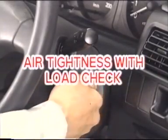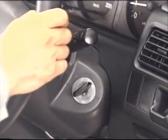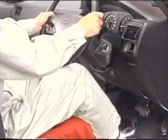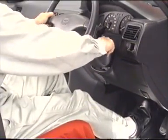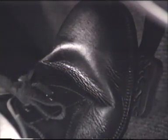Next, go on to check the air tightness with load. With the engine running, depress the brake pedal with a constant foot pressure. Stop the engine and check that the pedal reserve distance does not change for 30 seconds. This indicates that the vacuum in the constant pressure chamber is maintained.